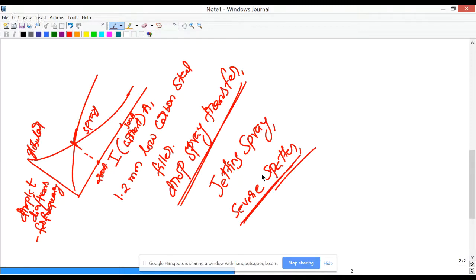The question reads, silicon and aluminum additions in steels retard cementite formation. How? Well, that's the answer I expected. They retard the cementite formation because of the low solubility of these elements in cementite, right? When the cementite has to nucleate, the silicon and aluminum atoms will be pushed out from the nucleation sites of cementite. And because of the low diffusion rate of silicon and aluminum, it's difficult kinetically. Therefore, the cementite precipitation is retarded.